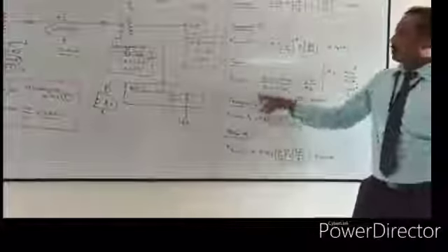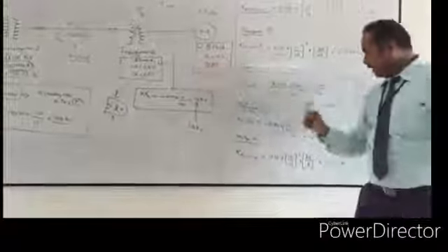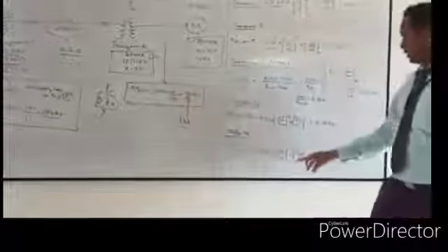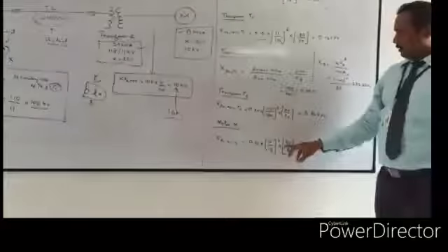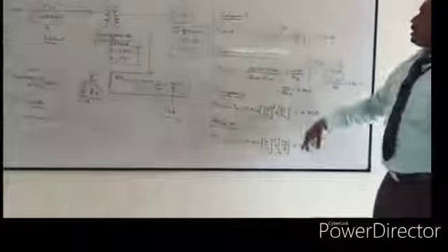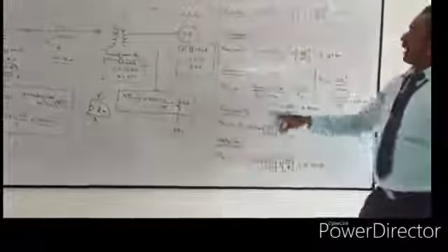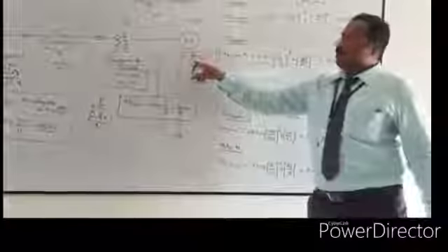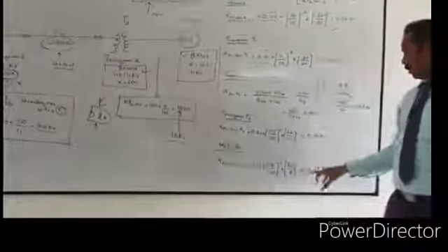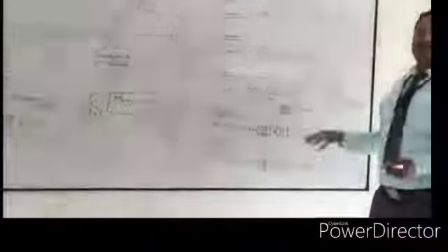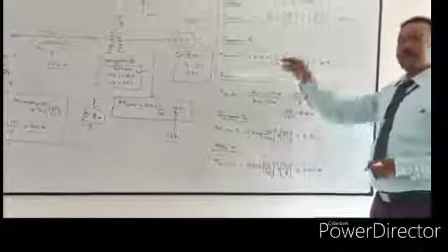What is kVp old? It is in the nameplate detail, 10 kV, and what is the kVp new? Which we have just calculated, this 10 kV is going to be the new base kV, and multiplied by MVAB new, which is common for all the components, 30 MVA, divided by the rating of the motor, the old MVA value, which is 8. So 0.375 per unit.